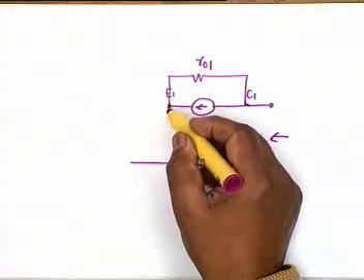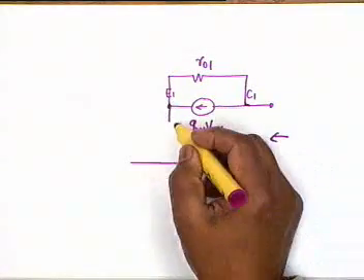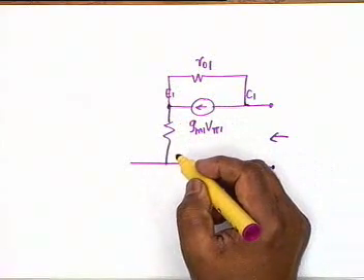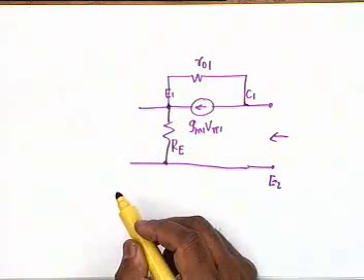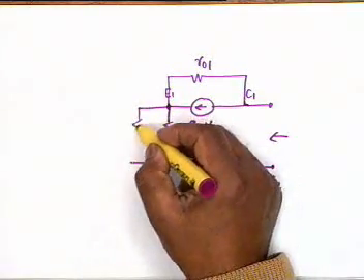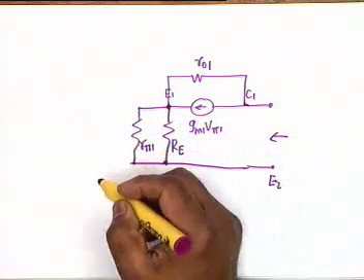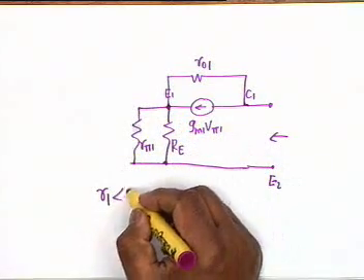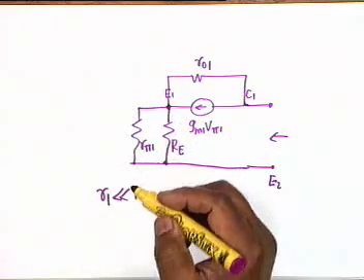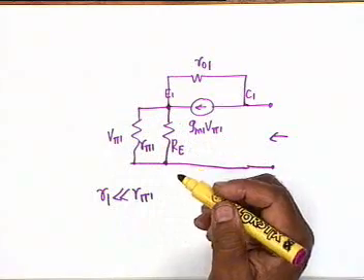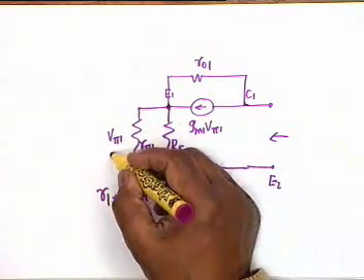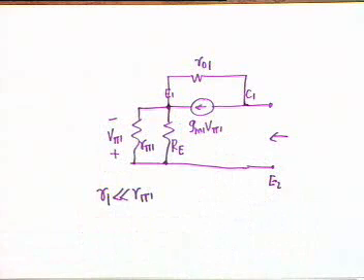Yeah, this is E1. Between E1 and ground there is a resistance of R. And in addition from E1 R pi 1, because we have ignored R1, R1 is much less compared to R pi 1, and the potential difference is, which terminal is positive, lower one or upper one? Lower one. That is it. This is the equivalent circuit by ignoring R1.